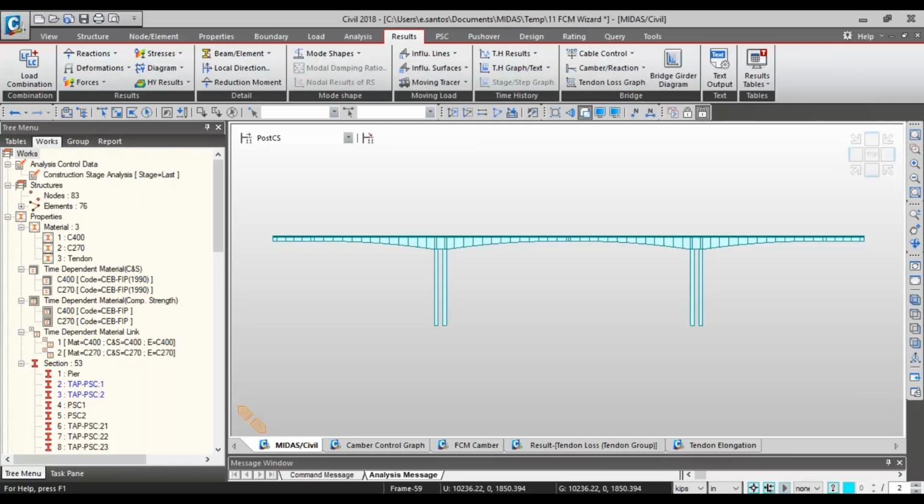So, unknown load factor. For those of you who are not familiar with the unknown load factor, this function basically optimizes the tensions of cables at the initial equilibrium position of a cable structure. The program can calculate the initial cable force by inputting restrictions such as displacements and moments. You can tell the program that you want a particular force, and it will try to satisfy those constraints. So, how do you use the unknown load factor in the program?